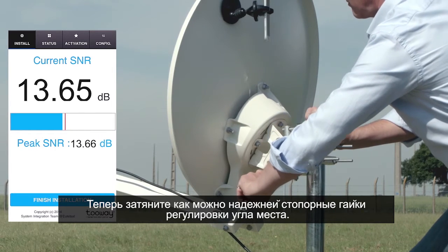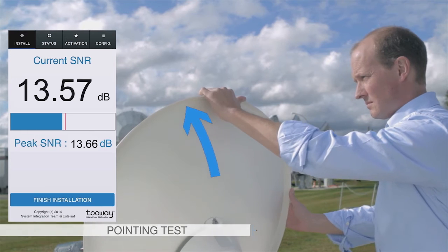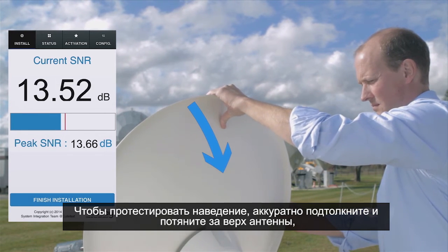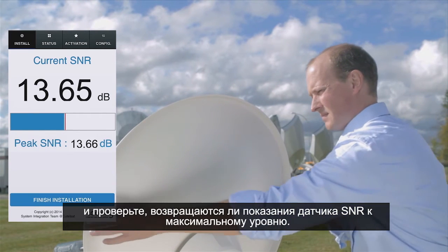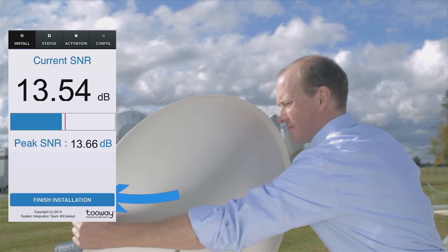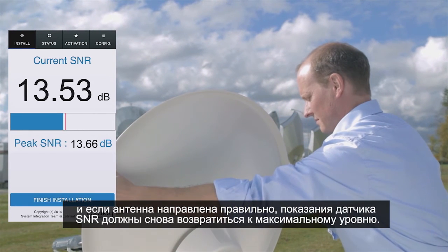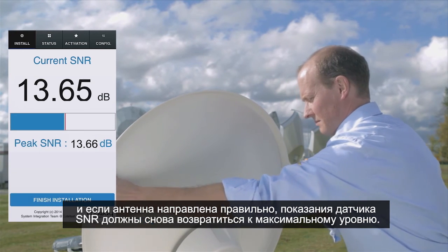Now you tighten off the elevation locking nuts as tight as possible. To test the pointing, gently push and pull on the top of the antenna and see if it returns to the SNR max level. Then push and pull on the sides of the antenna, and again it should return to the SNR max level if it is pointed correctly.